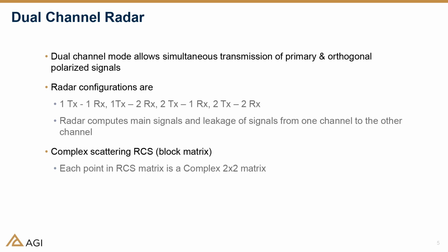One can also think of a dual channel radar as what some weather organizations use. They use what's called a WSR-88 weather radar. The really big use of a dual channel in these cases is not only that it allows you to detect certain weather patterns that are coming in, but it allows you to determine what exactly the clouds are made up of. So you're able to determine, is this a snow system coming in, a hail system, or a regular rainstorm? So with the dual channel, it does give you a bit more fidelity that you wouldn't have otherwise.